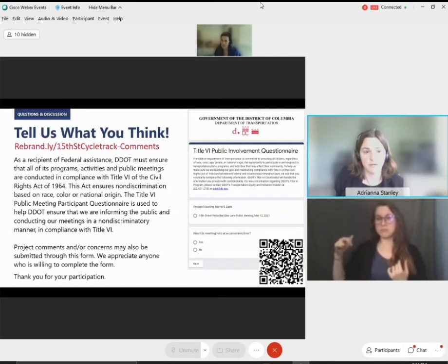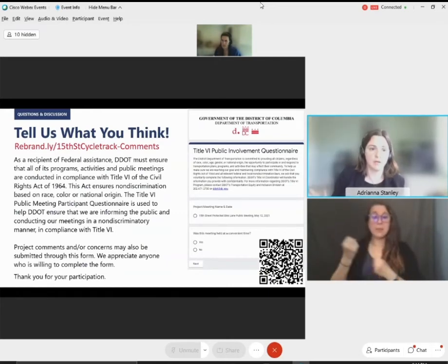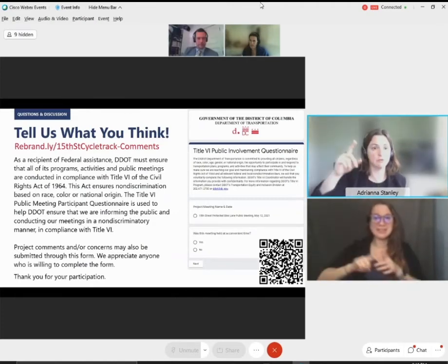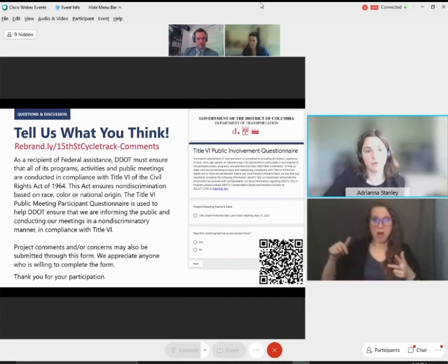We're also providing, where that isn't the case, so where the cycle track isn't the driver and where turning movements are also happening, what's called a leading pedestrian interval. So pedestrians get a couple of seconds to begin their crossing movement before vehicles see a green light. That gives people a chance to be out beyond that conflict point or more in the view of a driver before they're going to be executing their turns.